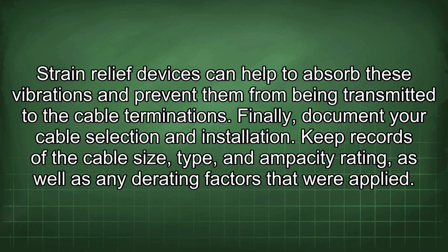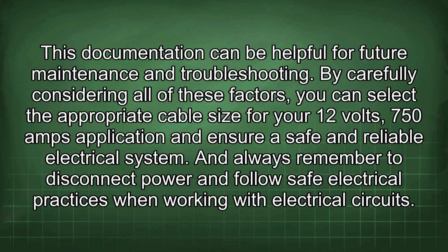Finally, document your cable selection and installation. Keep records of the cable size, type, and ampacity rating, as well as any derating factors that were applied. This documentation can be helpful for future maintenance and troubleshooting.